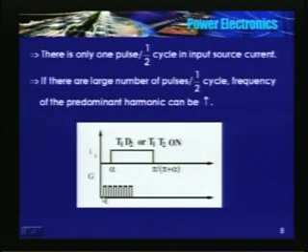Definitely looks like a device is turned on at this point and device is turned off at this point. There are a large number of pulses. Zero current implies devices are off, or source current is 0, it implies that the power source does not supply power. Current may be freewheeling in the load, that is okay. So the device must be turned off at this point when the current becomes 0.